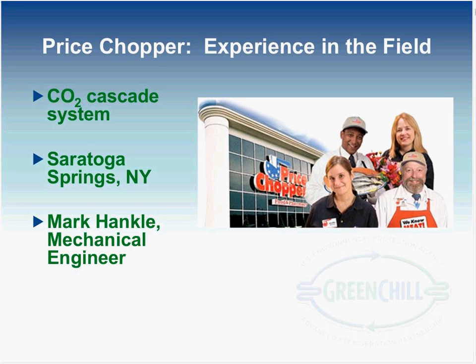I think Scott or Travis had mentioned earlier that in the infancy of CO2, most of these components were readily available in Europe, but not here in the U.S. So long lead times were not acceptable. So we're able to work with our compressor manufacturers and rack manufacturers to help support us in that need. To date, I don't believe we replaced one compressor, and I think our first CO2 system is approaching 3 years now.